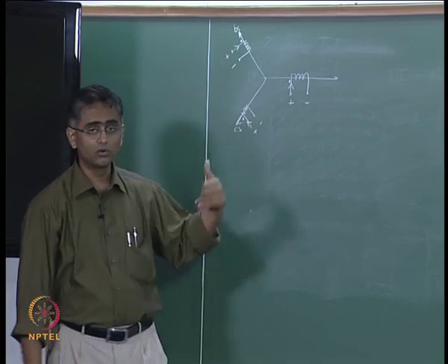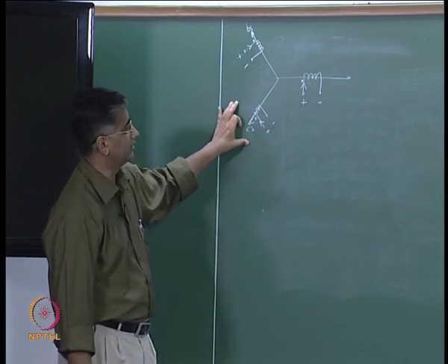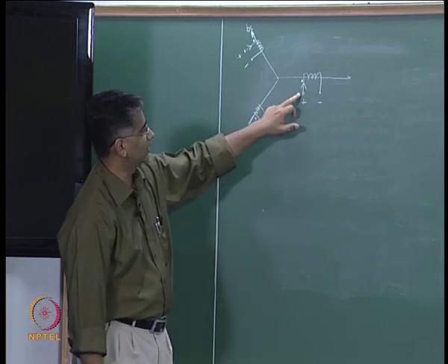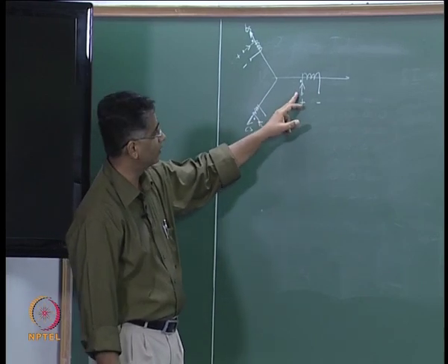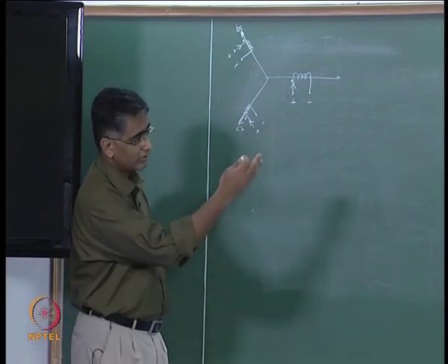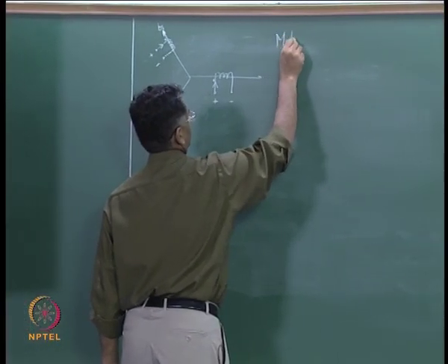This convention holds good for the induction machine as well. Now, what this convention means is that we have assumed that the reference direction of current is one that flows into the terminal marked plus, and therefore the equations we have written down follow the motor convention.